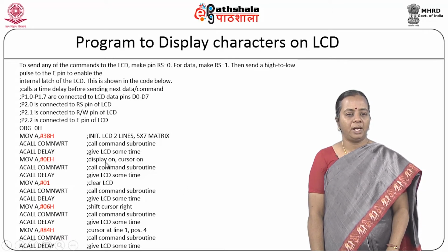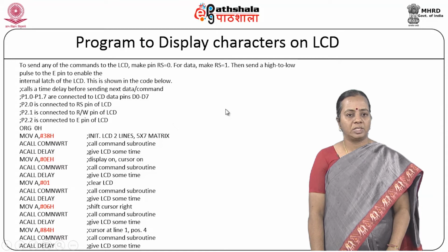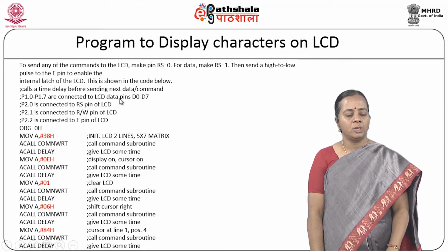So, these are the primary setups which we have to do with your LCD before sending the data to display. Another thing we need to recognize is that each and every time I am sending a command to your LCD, the LCD needs a time delay so that it processes that particular command, or if I am displaying data, that data has to be displayed. So, there is always a time delay following the command or the data to be displayed.